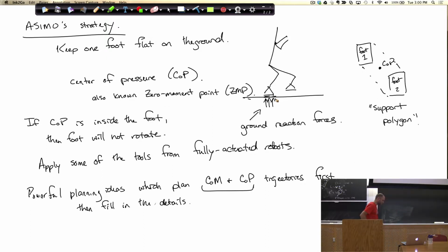And then if you think about the goal of keeping your center of mass at a constant height, now you want to take your longest possible step with your legs mostly straight. Okay, that means if your center of mass is at a constant height and you have to be able to step like this, then there's going to be this awkward fact that when you're at the normal stance, your knees are pretty bent, and everybody for the rest of time is going to ask you, why do you walk around with your knees bent, right? Life goes on. But that's why the robots are walking with their knees bent, because they're trying to keep their center of mass flat.